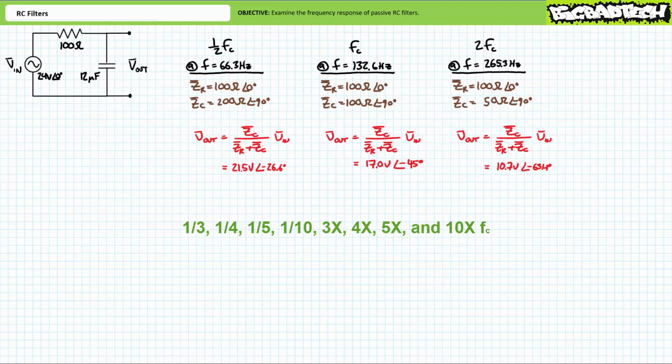Just kidding. This is obviously a lot of tedious busy work best suited for a computer. In fact, the analysis of filter circuits is one of the rare occasions in which I find computer simulation to actually be better than a hardware lab, simply because of all the tedious busy work involved. Many software-based circuit simulators offer a frequency sweep or a Bode plotter, where the software simulator varies excitation frequency from a user-defined low to a user-defined high. The simulator then plots the electrical properties of the circuit of interest for the desired frequency range.